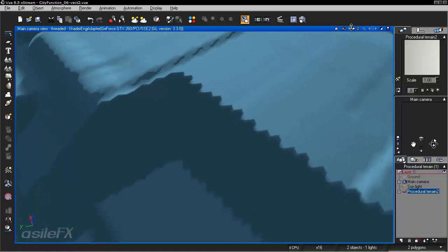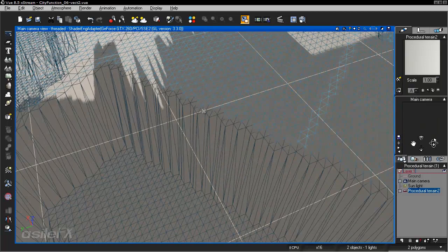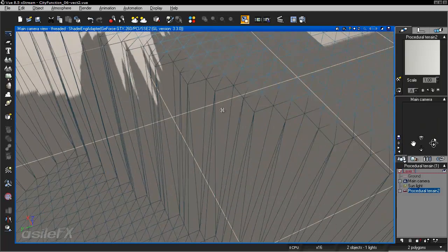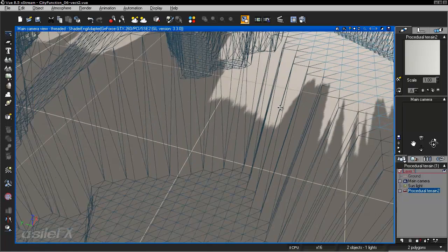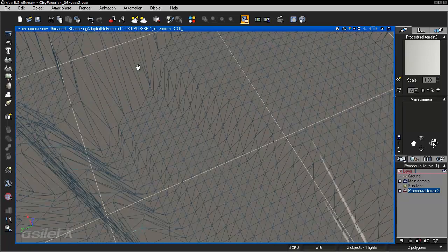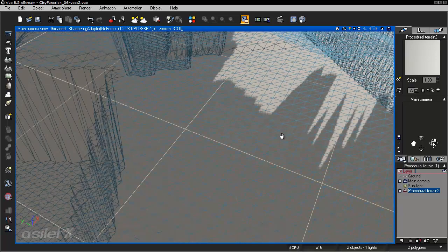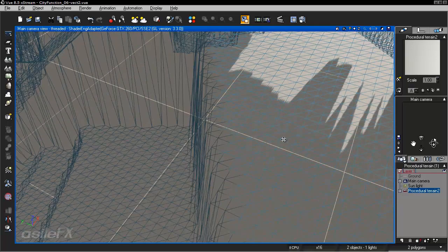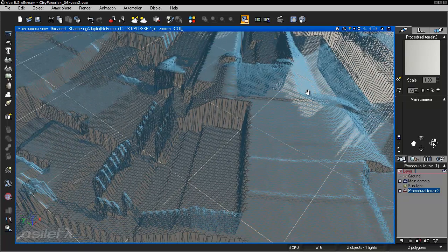We'll go ahead and switch this to the wireframe mode. So what we can see is the blocks and the way the polygons are set up. Instead of the division where it is split being the edge, it is right in the center. So we have these huge, just jagged edges. That is unavoidable whenever you want any sort of angular shape outside of the grid. So if you turn up the quality boost, it increases the geometry and it takes care of those jagged edges.